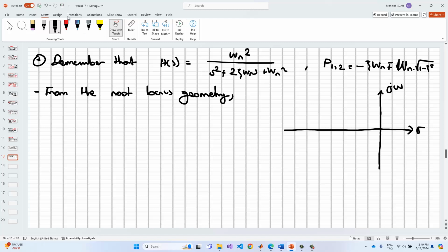And so we have the minus 6 pole in the open loop system, minus 4 pole in the open loop system, and also we have the zeros in the open loop system, okay? This is how we can transfer our root locus in here, okay?